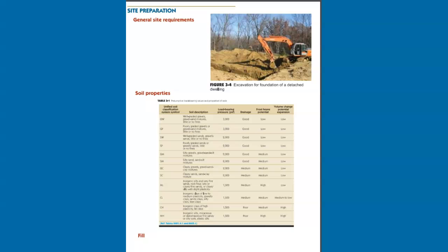In addition to organic materials, certain inorganic clays and silts are highly expansive. Such soils expand when wet and contract as they dry, exerting significant pressures against the footing and foundation and thereby causing shifting or differential settlement that could result in structural failure. Expansive soil conditions require an engineered foundation design in accordance with the International Building Code (IBC).